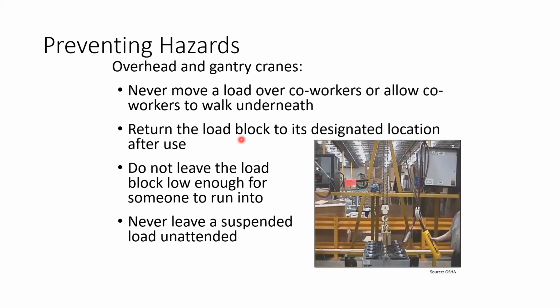For overhead or gantry cranes, how can we prevent the hazards associated with them? Number one, never move a load over co-workers or allow co-workers to walk under it.